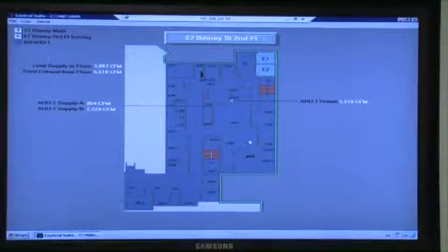I think you'd put a dot there and bring that out, Jamie, like this, on exhaust fan 16. It's at 0 unless you're purged. At this point, there is no airflow station on 16? On 16. Okay. Then we don't need to put it on there. It's not a normal system. It's not going to be normally running.